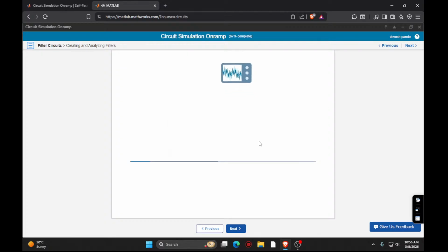In your vibration signal, you will see many frequencies. The steady hum of machinery in the basement, rumblings from trucks driving over a speed bump, and a constant 50 or 60 hertz from your lighting. But what you really care about is an experiment you're running that produces a high-frequency signal. So, before you can analyze your data, you need to filter out all those lower-frequency vibrations. You can do this using a high-pass filter.